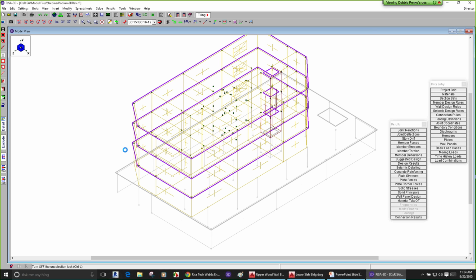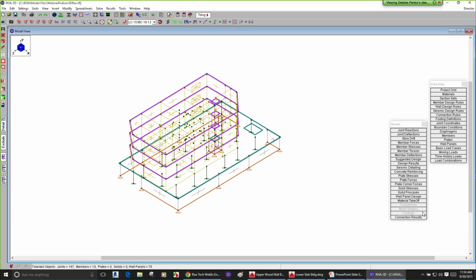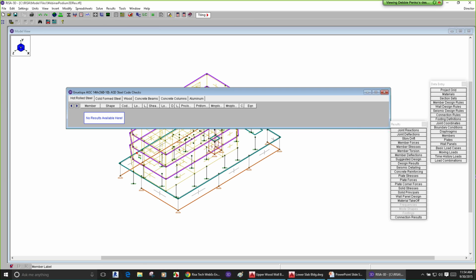I've just unlocked the rest of the structure. There's a lot of information here. We didn't actually bring any beams across because, for our lateral system, we were relying on all of our columns just to support the lower level, but otherwise your wall system is really the only piece that we had for our lateral system.